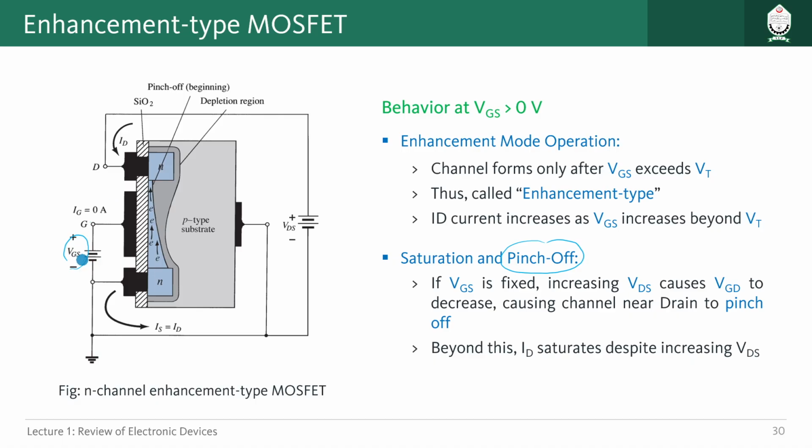And if you remember, we have this N type region connected with this P type substrate, and the drain is at a higher potential compared to this substrate, as well as the gate. The gate is also affecting this substrate because it is using an electric field to control the holes and electrons here. So what that means is this p-type substrate will be at a lower potential compared to this drain. As a result, this region here is actually reverse biased, and there will be a depletion region created because of this situation.